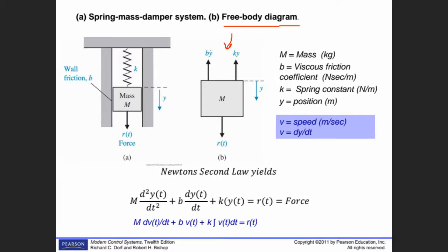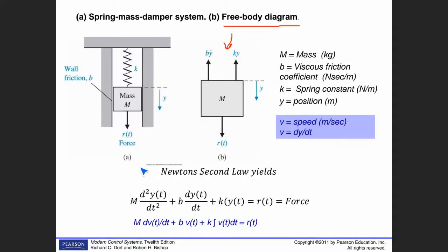So this spring system, we are actually pulling it with the force F. Since the system was originally in equilibrium, some forces are going to be against my force. One of the forces is the spring. The other one is friction here. So the equation is going to be this: M, y here representing the position, similar to x. M d square y dt square plus friction times dy dt plus k times y(t) is equal to the force in the time domain.